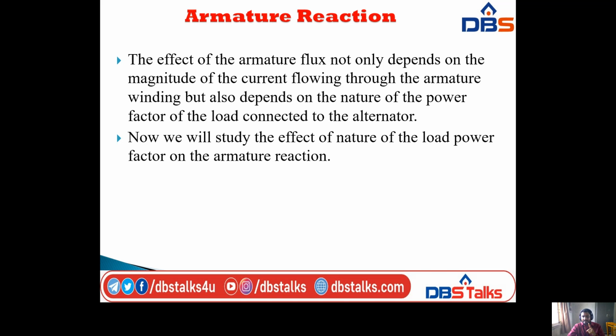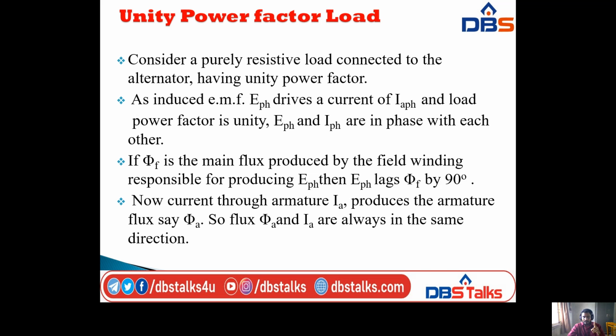Regarding the nature of the power factor of the load connected, we have three: unity power factor, lagging power factor and leading power factor. Now we will study the effect of the nature of the load power factor on the armature reaction using those three. Firstly, we will see unity power factor load. For that we have to consider a purely resistive load connected to the alternator having unity power factor.